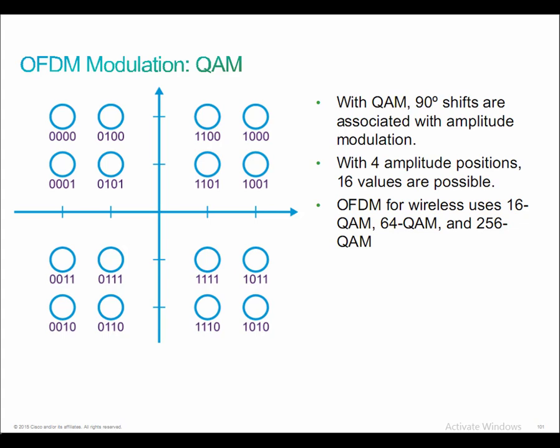And 2/3 of the bits are information bits and 1/3 are redundant bits. So it's simply a matter of increasing the ratio. If I increase the ratio to 3/4 information and 1/4 redundant bits, then I get to that magic number that we're all used to seeing with OFDM, which is 1.125 megabits per second per carrier times 48, which gives us a speed of 54 megabits per second. Okay.